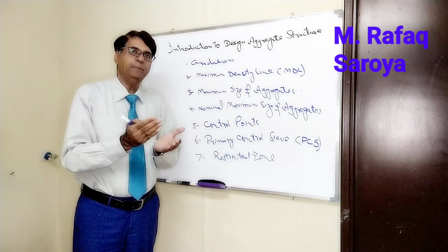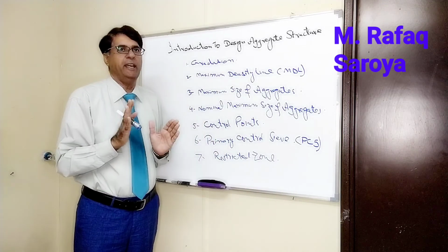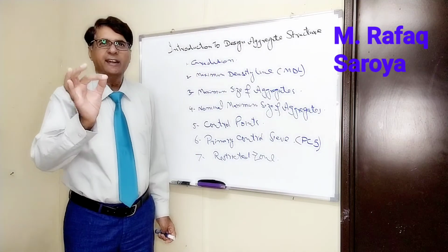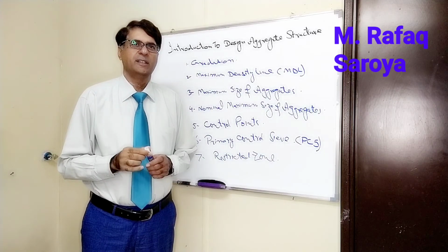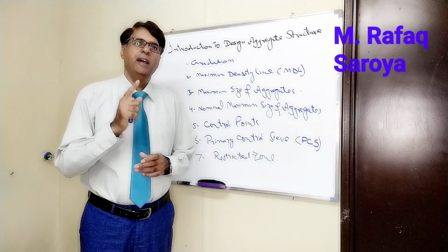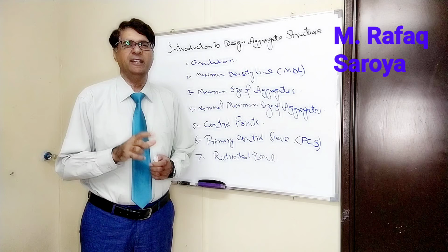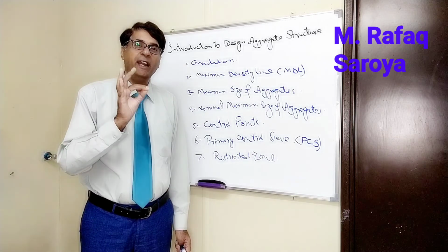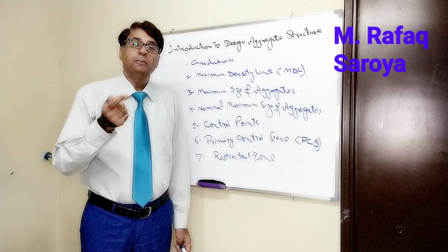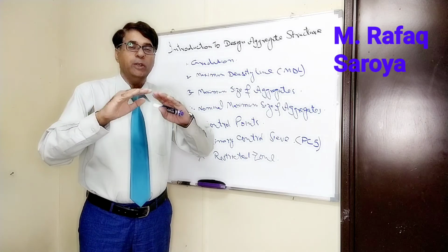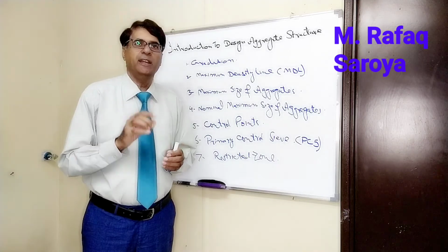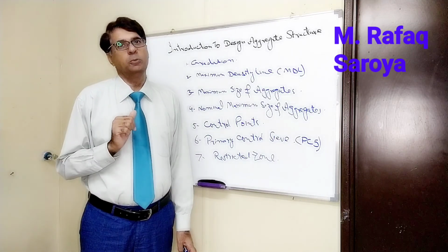When the broad concept is developed in your mind, then we will be able to design the design aggregate structure. Here, just for introduction, I will tell you, like in Marshall, we were making one structure. Here, when we develop the Superpave mix design, one is not sufficient. We will have to make either 3 or more than 3 structures. From those, we will see which one most accurately meets the criteria set by the Superpave specification.